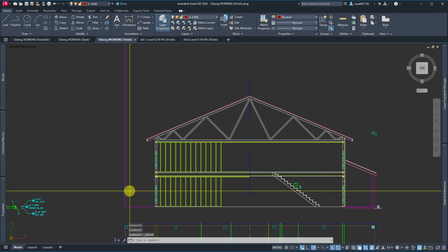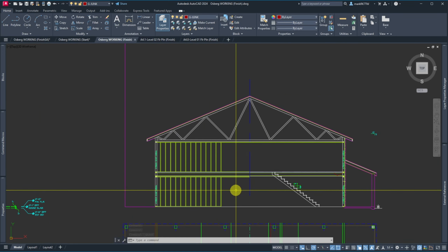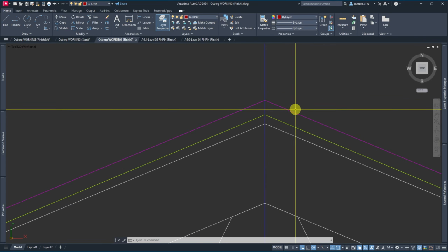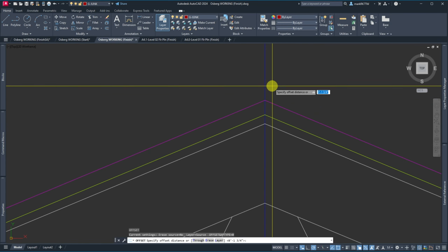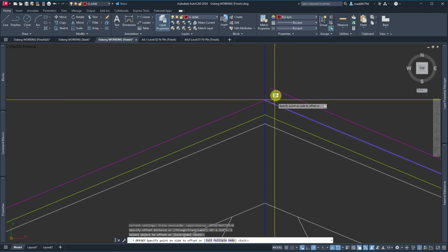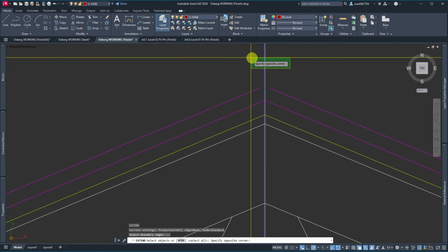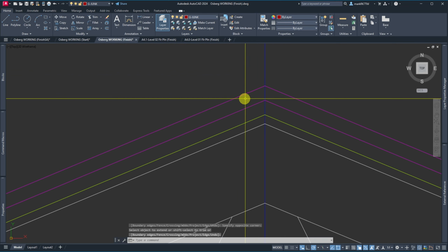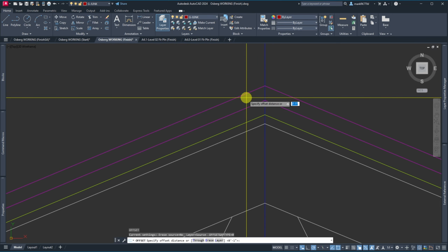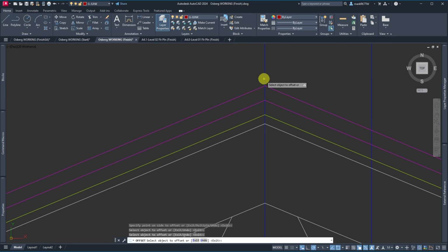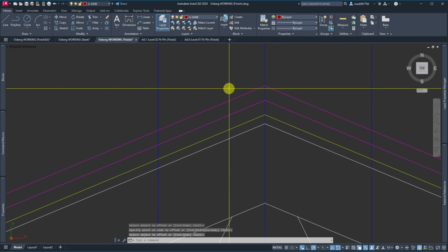And we basically have ourselves a completed, oh, we want to put the ridge vent on this thing. So one thing I've been doing is just offsetting one, because I use another piece of software along with this called Chief Architect, and it likes to draw the vents at 1. Right now I'm just offsetting 8 because I haven't gone in to check and see what the width is on them.